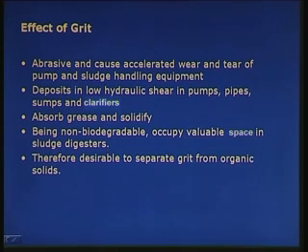So, they keep on accumulating as a function of time. Therefore, it is very desirable to separate grit from the organic solids. Organic solids are biodegradable, they undergo a change, they are non-conservative, while the grit is a conservative chemical, it cannot change. So, it occupies the space. That is why we should remove the grit from the wastewater before it goes to the secondary treatment.